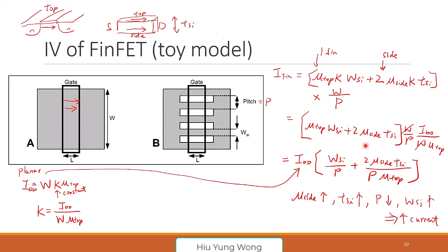Any question here? So those ones for the tri-gate FinFET? Yeah, this is actually tri-gate. You're right. You can claim that, oh, you should not call it FinFET, just call it tri-gate. But not really important to distinguish. Yeah, because we're actually considering 3 terminal. And if it is a real FinFET, then we don't have this term. You're right. This one will be gone.